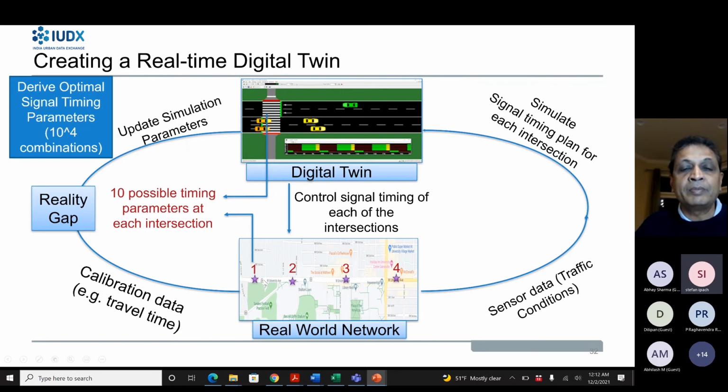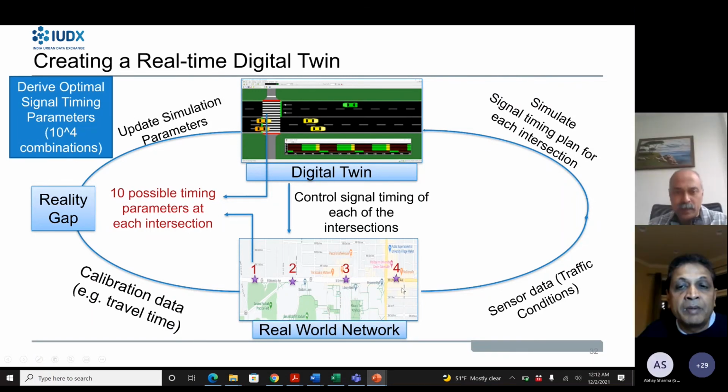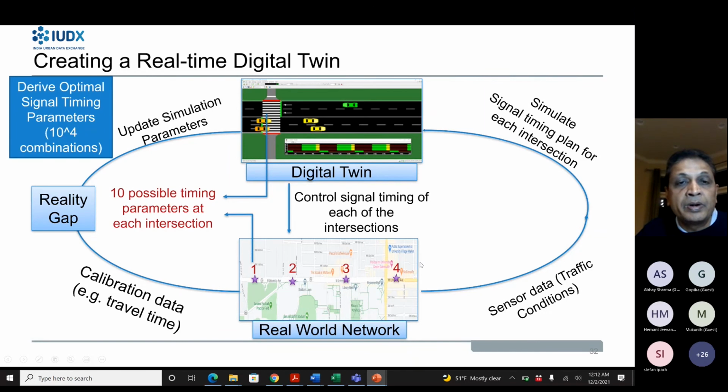Most corridors, the way they are set up at a very simple level, is that the cycle time for each of these intersections is roughly the same. And then you say, look, how much time do I assign to green phases, and how do I do a phase offset, as they call it, for these intersections is decided, right? So the problem, unfortunately, is that several parameters need to be optimized. So let's say even there are 10 parameters for each of these intersections in terms of how do you divide up the cycle among the different phases, how much time to give to pedestrians, because the traffic behavior on each of them may be slightly different from each other, right? Because their minor streets have different behaviors. Or in some cases, they may be on a hub where there's a major street on the perpendicular direction also.